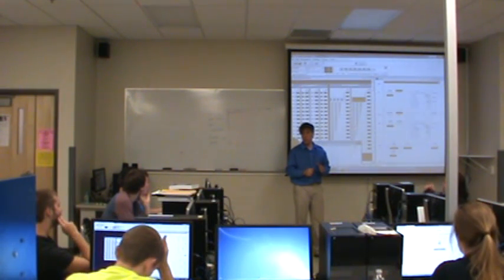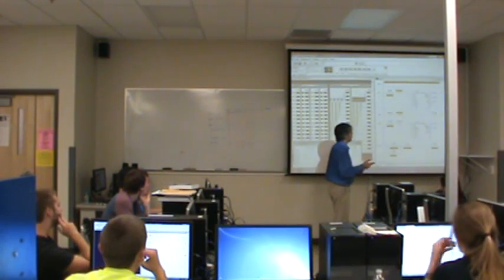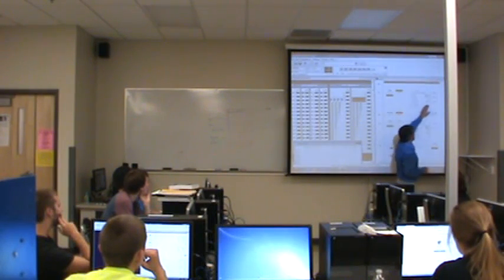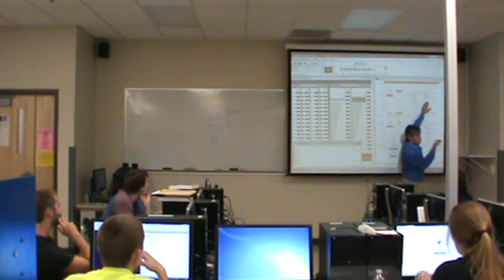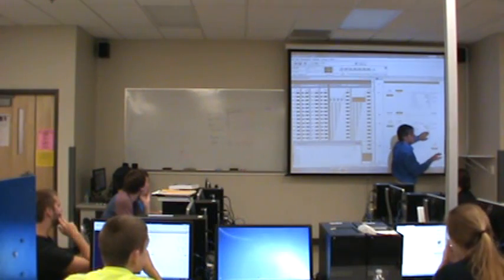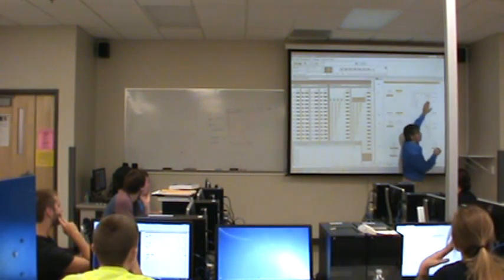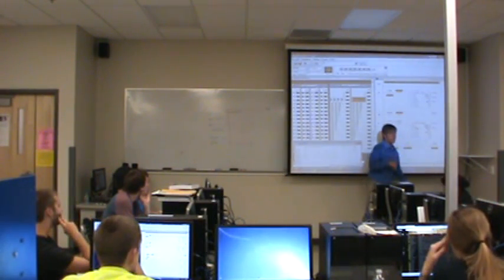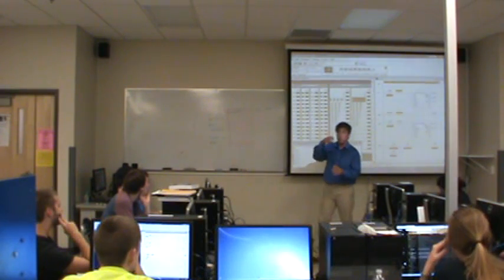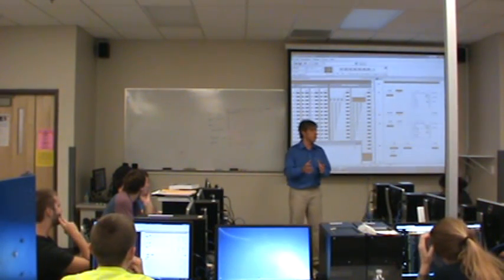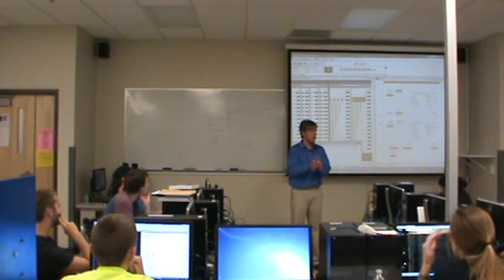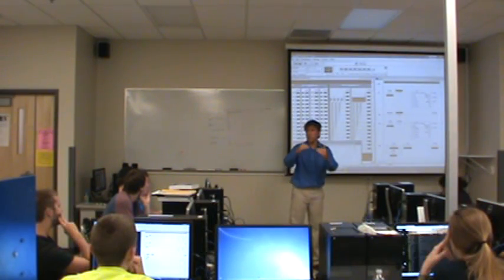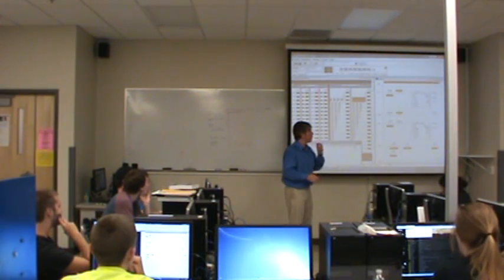Does that make sense? So there are sequences that have to happen over and over where you have to look at a bunch of inputs, see what they're doing, make sure they're in the right order, and then set a bunch of outputs. And then go back and look for the next set of inputs. The next set of inputs, after you've opened the bag and you're filling the bag, maybe is the bag full? So there's a sensor that detects when the bag is full, and then you need to move on to the next step of closing the bag.